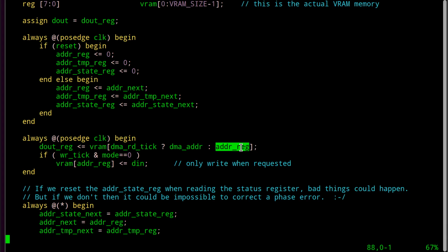We'll see when we look at the rest of the code, the state machine and another mux thingy that I put together. What we do is we always read from the memory and we cache the output value when we're not doing a high priority state machine access. Whenever we read from the address counter, and we do it before the CPU even asks, we store it in our registers elsewhere, so that we have it handy should the CPU ever need access, okay? After which we advance this address.